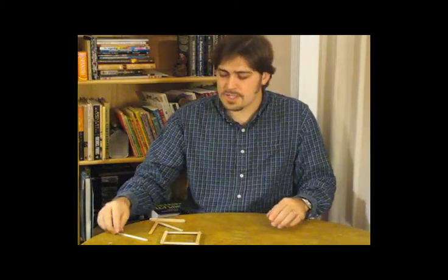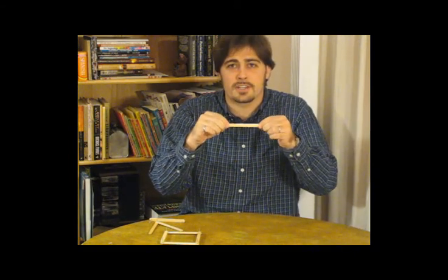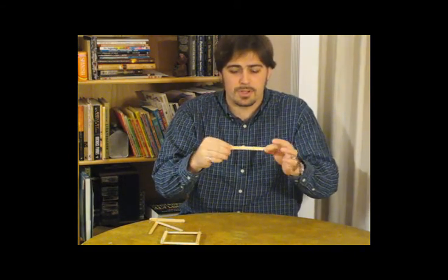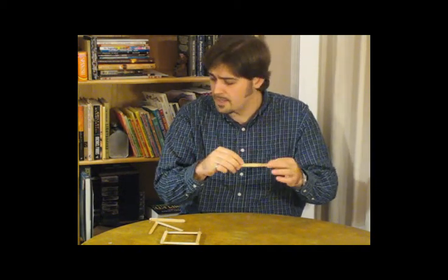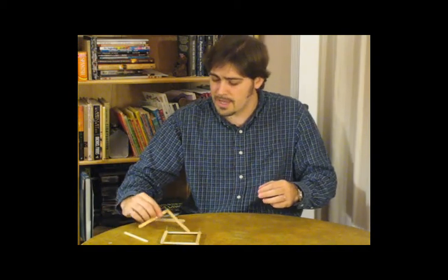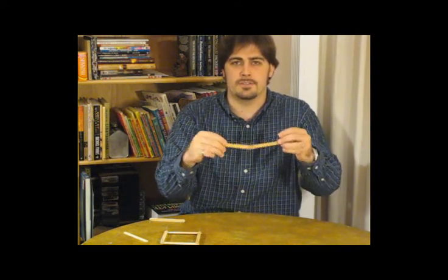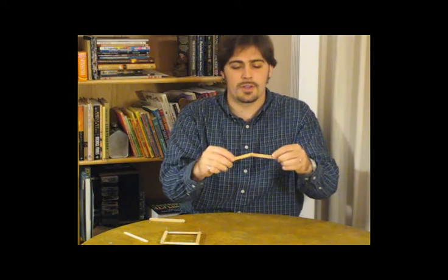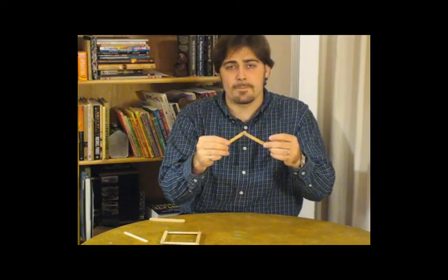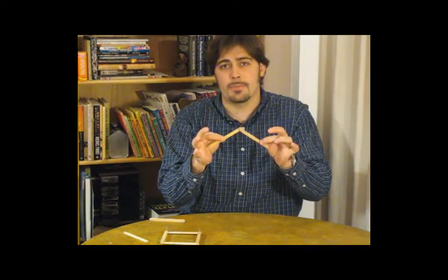Well, let's make a couple of assumptions first. First thing we're going to assume is that our members are not going to significantly change in length. So the member that we put in place in any kind of structure, we're assuming it doesn't change in length at all. And the second assumption we're going to make is that our members will completely freely pivot, just like this set of members I have right here. They will freely pivot one relative to another. Another way of putting that is to say that one member will not react a moment onto the other member.